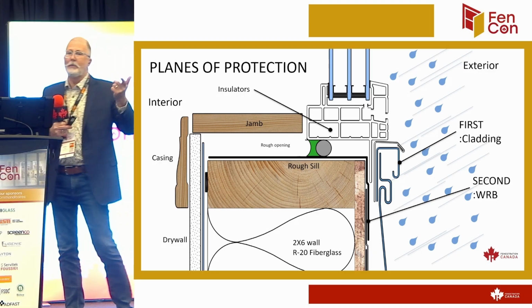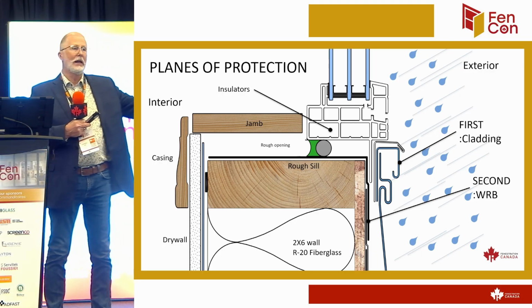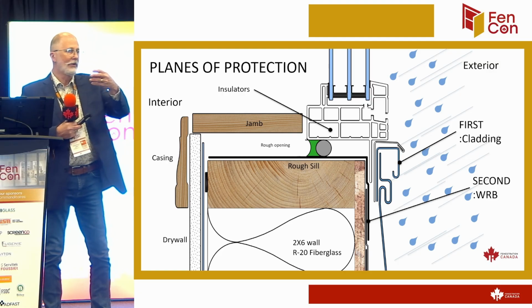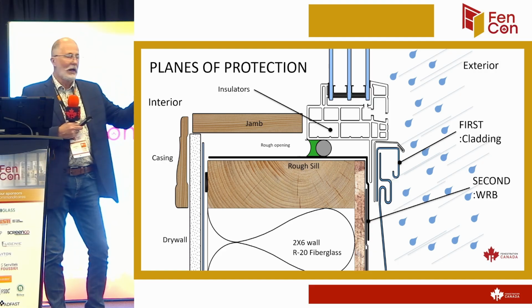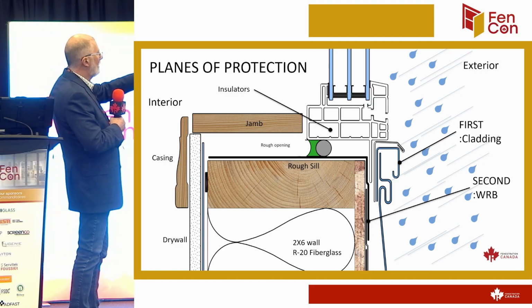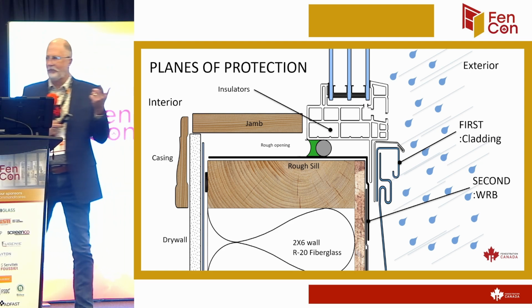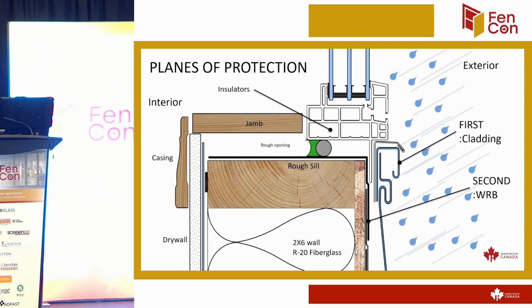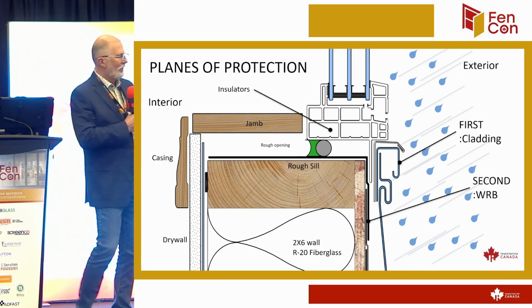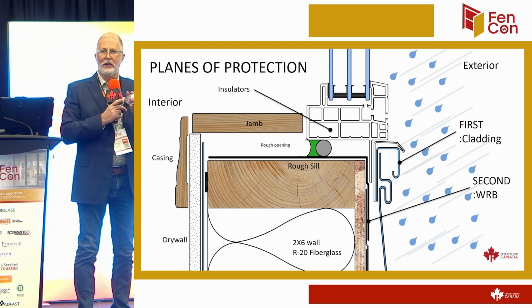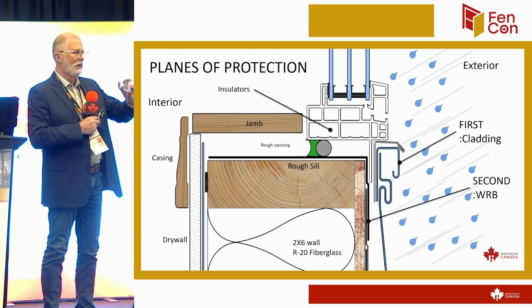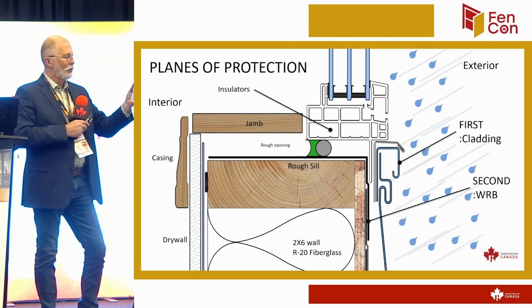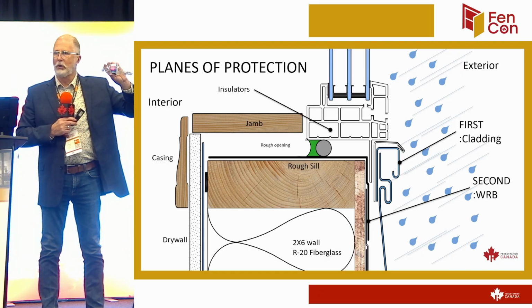What if it's raining? It's the summertime and the air is flowing from outside to inside and the rain is hitting there. Does it not pull that rain into the cavity as well? So that's the other problem with having that interconnected, if we don't have a good air barrier there. I illustrate it sometimes using a water bottle. If I take this water bottle and I pull the lid off and I turn it sideways, if this is the outside of the flange, I got about a 3/4 of an inch hole there, right? If I take the lid off and poured the water out and tried to blow air in here, how much air could I blow in there?